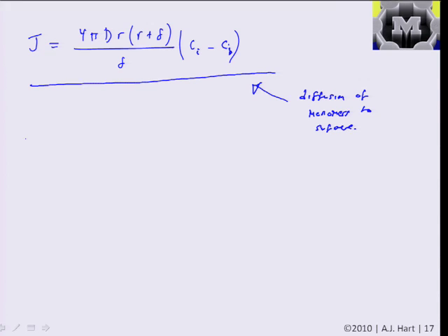And now if we look at the reaction at the surface, because all the monomers that diffuse to the surface need to react at the surface, we can write another equation that accounts for the reaction rate at the surface. Because we're assuming the reaction is in steady state, all the monomers that go to the surface react. It's not like they arrive at a faster rate than they react, and you build up a layer of monomers ready to react at the interface.